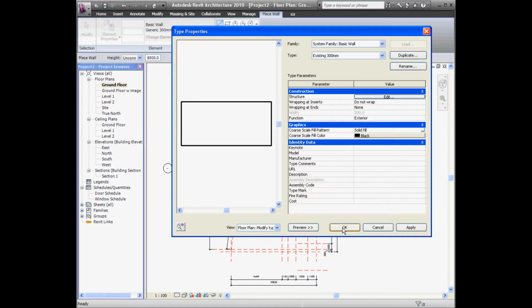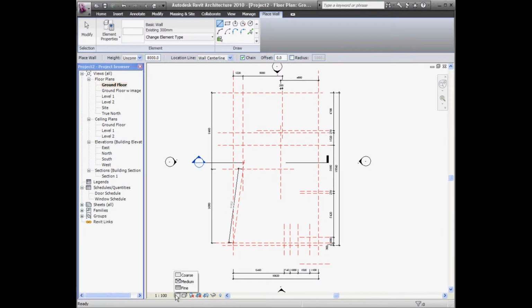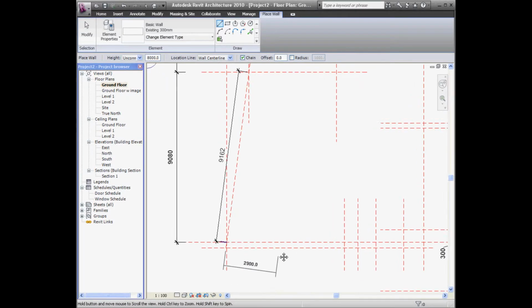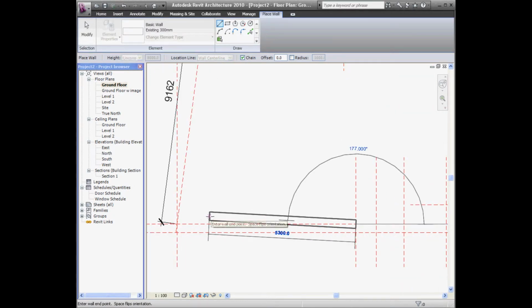Because otherwise it's going to change the original wall type and you don't want that. So now, I'll just show you if you've missed or haven't seen that setting before. It's in your view. You've got coarse, medium and fine. So that determines whether it uses that coarse material in the wall. And all your system families are the same. Floors, roof, ceiling, they all have a coarse material.